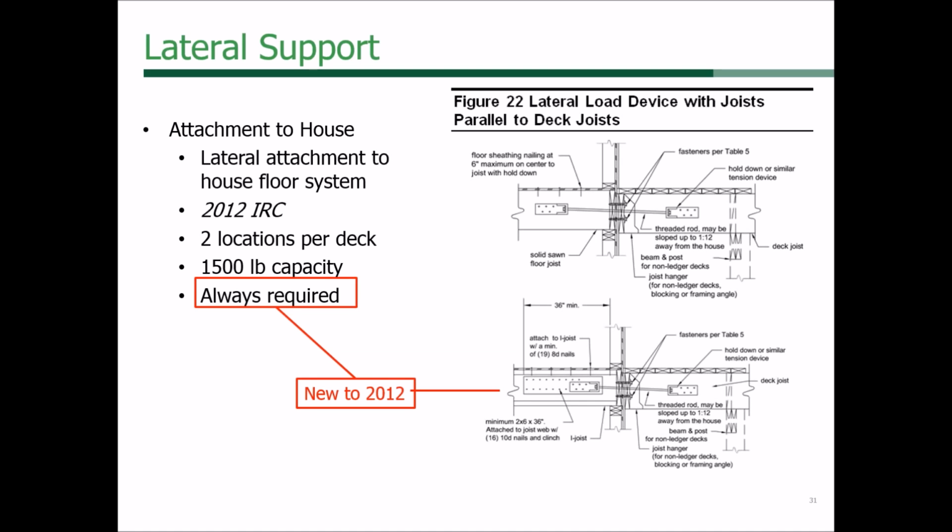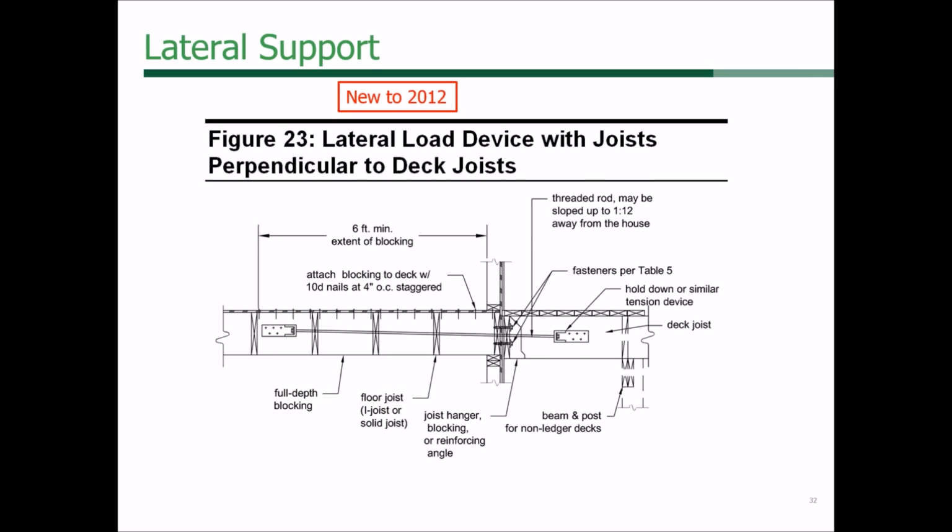And there's still research going on into lateral loads. This is another detail that you won't see in the IRC, for when the deck joists are perpendicular to the house joists. It is a very ugly detail, as you can imagine, that would be very hard to install, but unfortunately that's where we're at the moment.